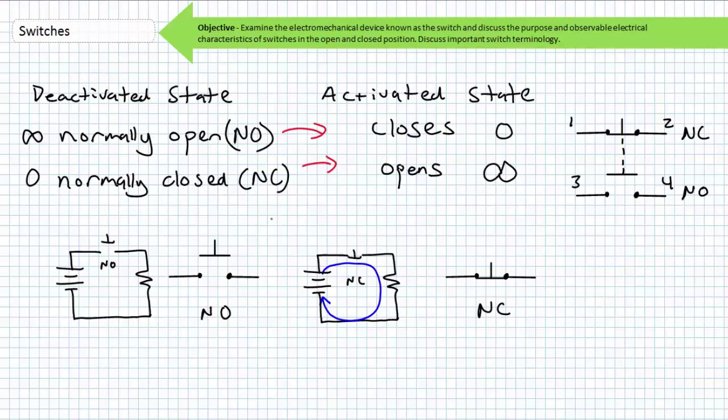I feel like I'm opening a barrel after barrel of rage-infected monkeys here by introducing tricky definition after tricky definition. But for now, just think of this as 2 electrically isolated, yet mechanically interlocked switches, both with double break contacts. This is often called a break-make push button because when you actuate the switch, the top switch opens and the bottom switch closes. Such a switch package might be employed to our advantage by turning off or preventing one electrical load from being energized when another is being turned on.